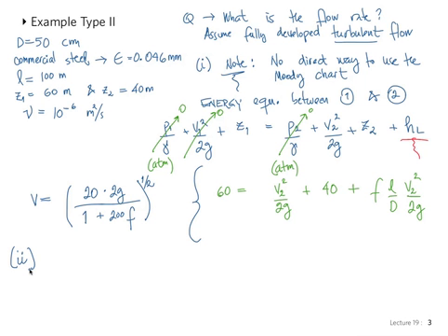Any guess? Okay, that gives us the roughness. But we don't have Reynolds number, so we can't go in the Moody chart. Take a guess. That's what we do. We make a guess.